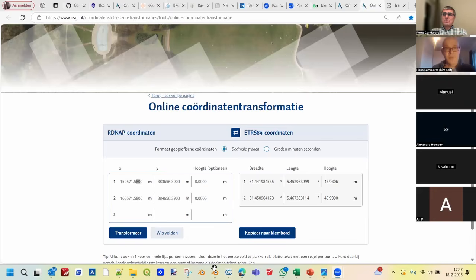But in the geospatial aspect and in GIS data, it's all meters. And in the BIM domain, we do everything in meters. At one point you have a conversion between meters and millimeters. It's just a value 0.001. It's a scale factor.